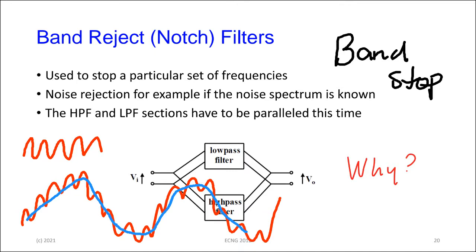And there are many, many others in audio and video applications, in automotive applications, and communications, and so on that you're going to meet, right? But how they work, again, the same principle is there. It has a center frequency. It rejects everything around that center frequency. So it's like the opposite of the bandpass. There's a center frequency and a bandwidth.